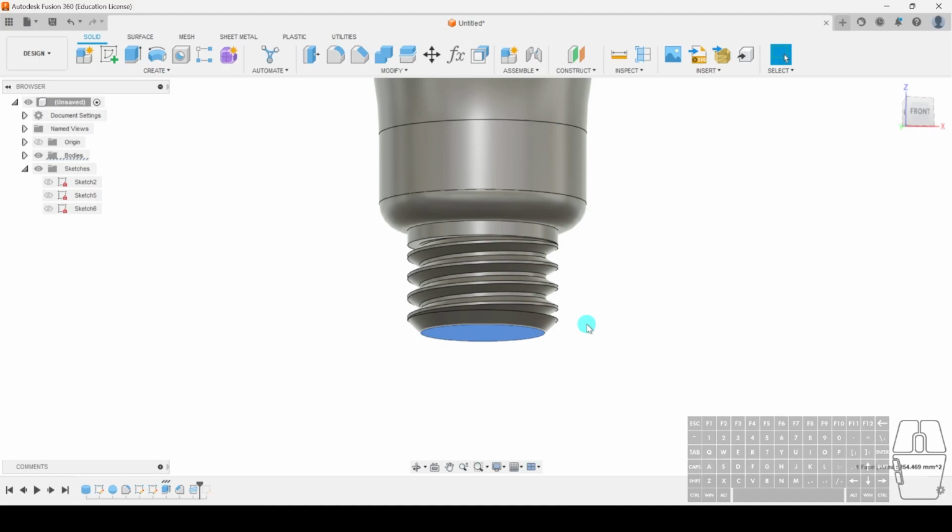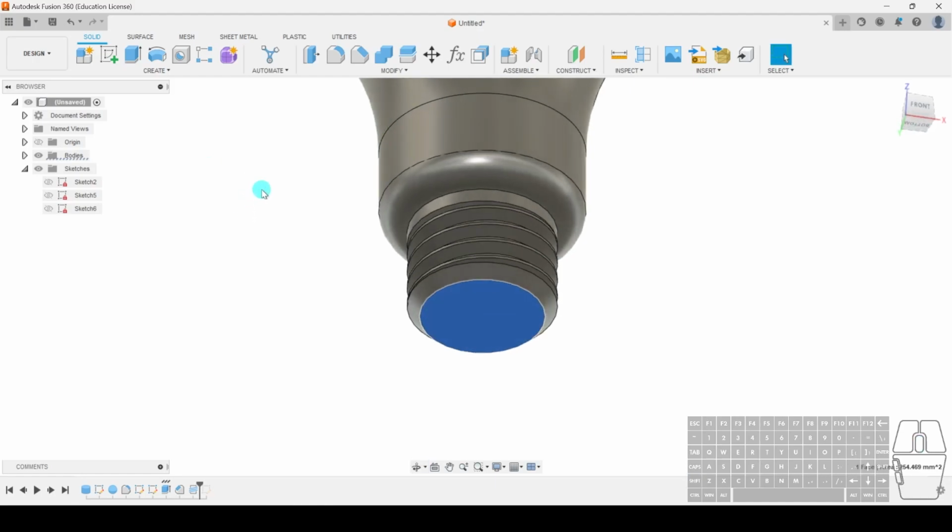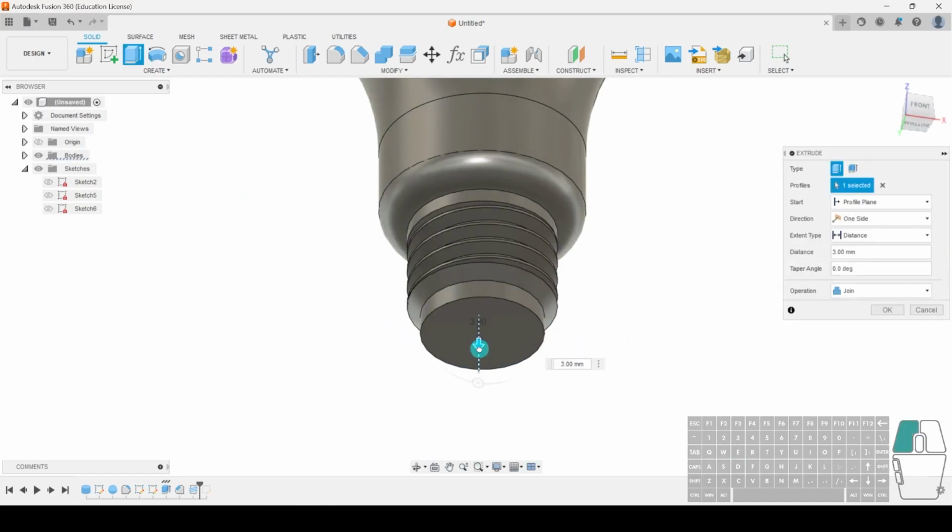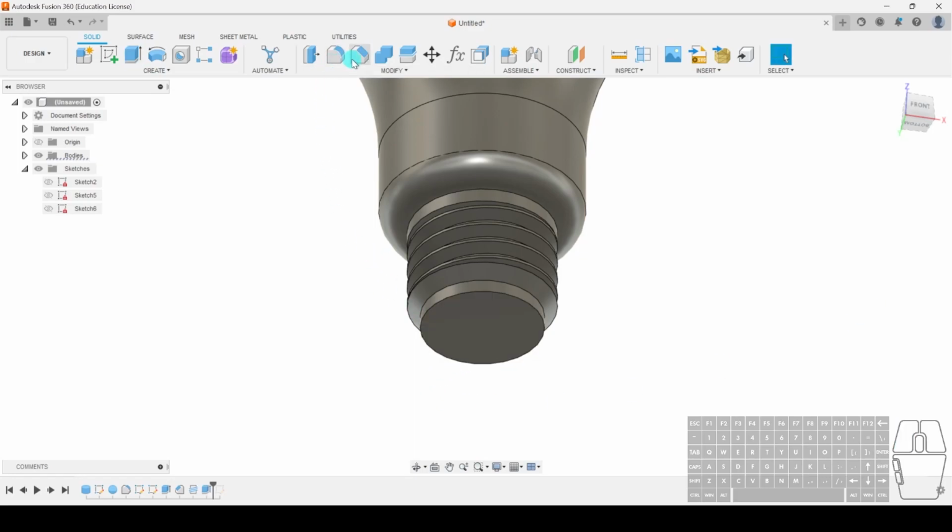This is the thing that pushes on the bottom and shows the disc contact. In this case, again, we don't need this to be super fancy. We'll just select the face. We'll extrude it down by about 2 millimeters. Was it 2? Yeah, 2 millimeters. Hit OK. And we will just chamfer this down again.